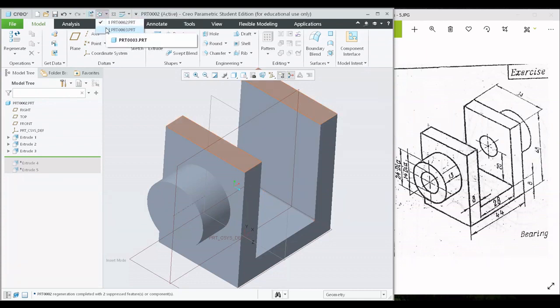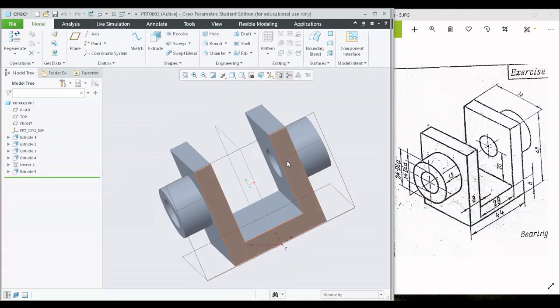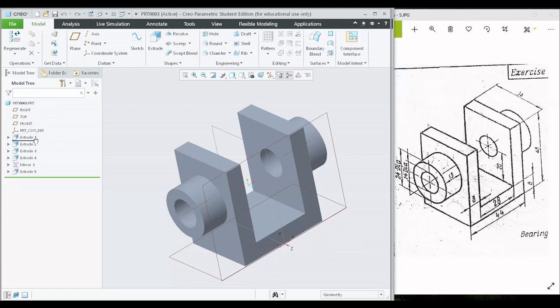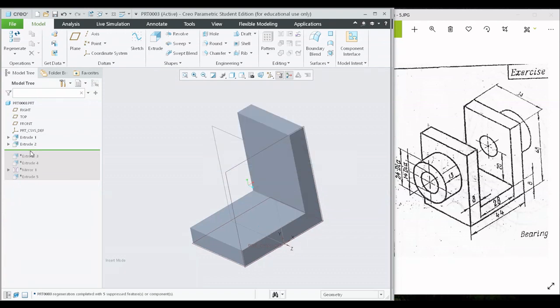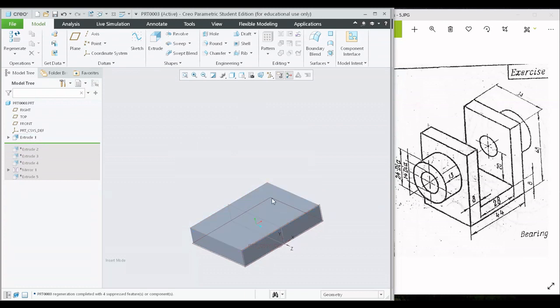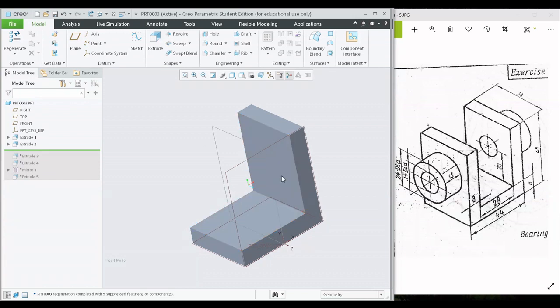But in this particular approach, we have not performed the same way. We have created the extrusion of the base, and then we have created another face, then we have followed with this face. So this procedure is also correct, because right now I am assuming that the first base is a raw material given to me. So after which I am going to weld this particular raw material on the right hand side to form a L shape.